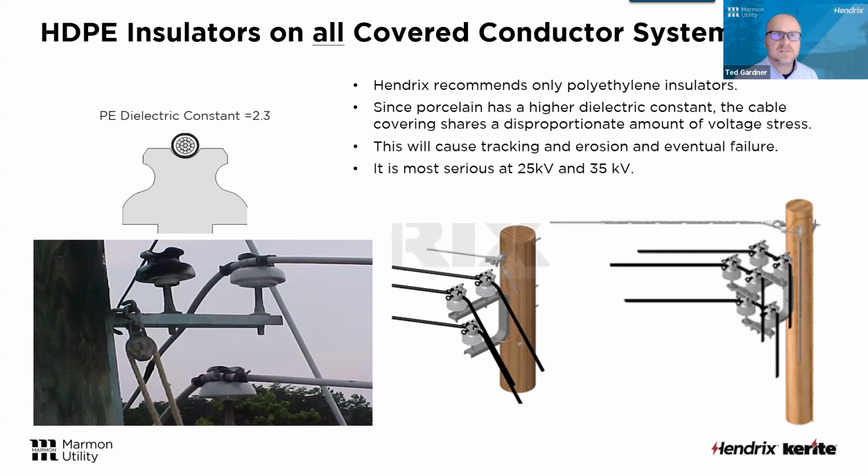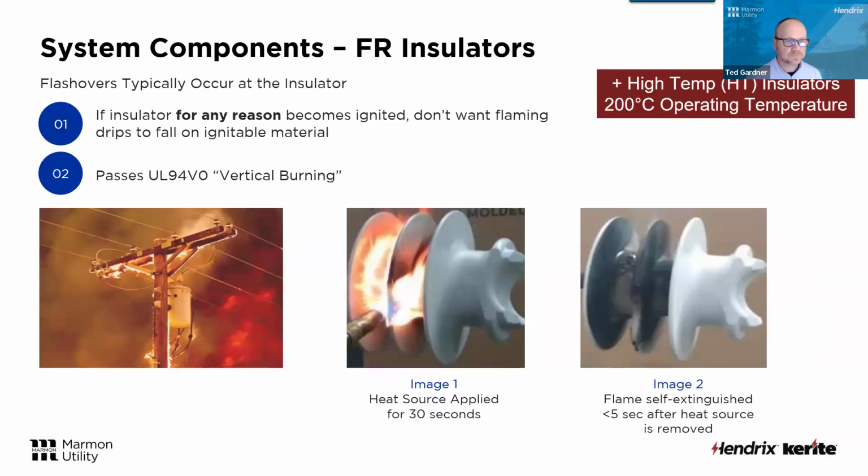And then about 10, 15 years later, the late 70s, early 80s, I think it was, we developed our vise top insulator. And that just took things a step further. Still all made out of the same high density polyethylene, but like I said, it eliminates the need for any ties. So that's our standard offering. But one of the things we recommend, for covered conductor, whether it's tree wire or spacer cable, is using a polymer insulator. The best thing we recommend is a high density polyethylene insulator, like we manufacture.